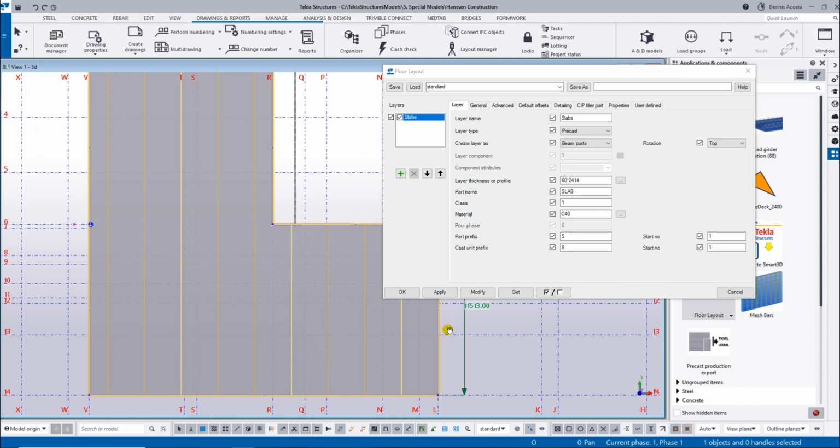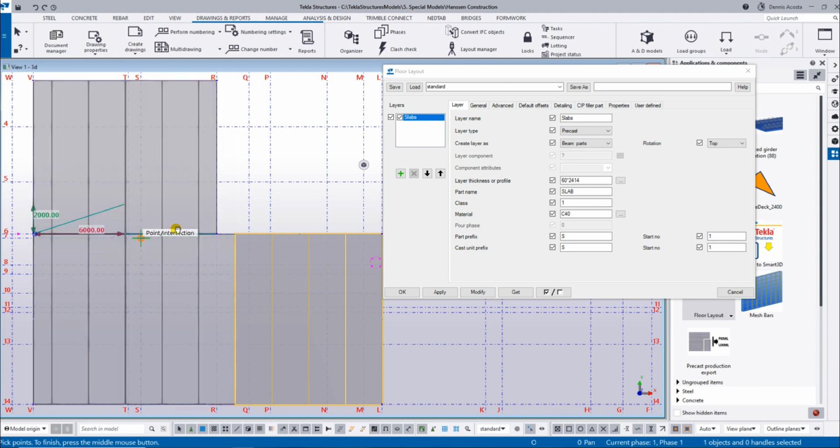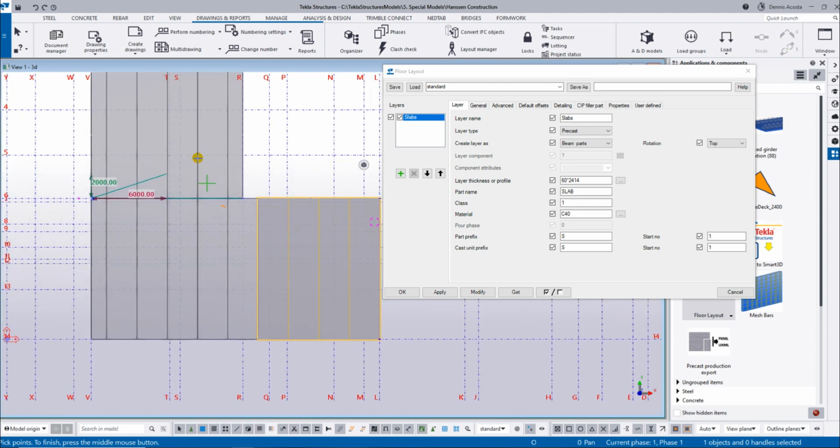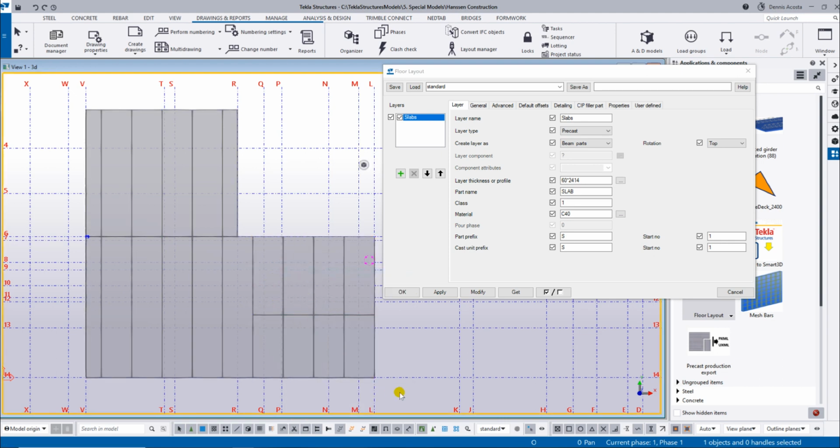So let's say, for example, for the length, I can use this direct modification and then use this splitting. I can simply click on this, and there you go. I can split that into two sizes, or even here, if I pick from here to here, I can split these elements. So that one will be individual. If I select the object and component, that will be an individual slab. So that's one way of modeling the slab.